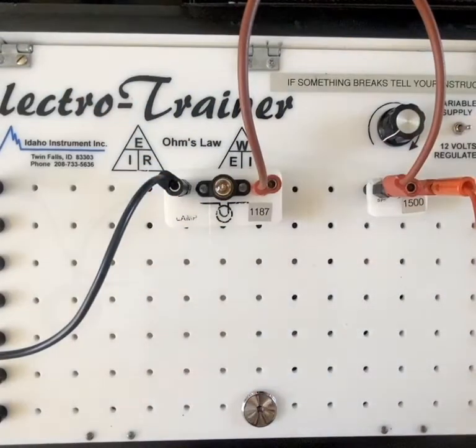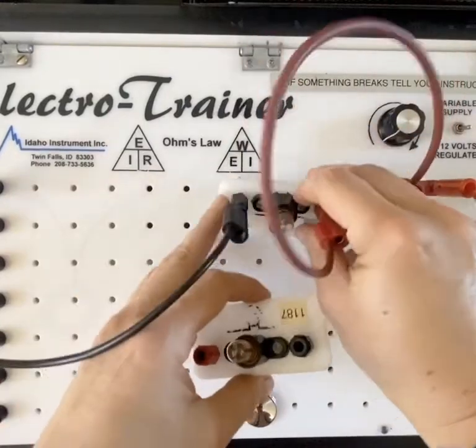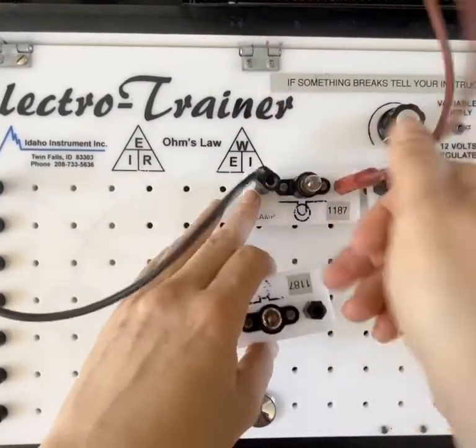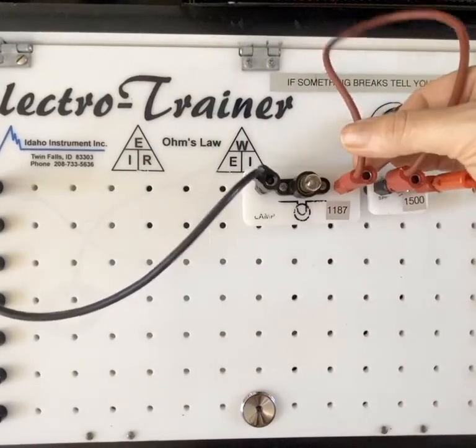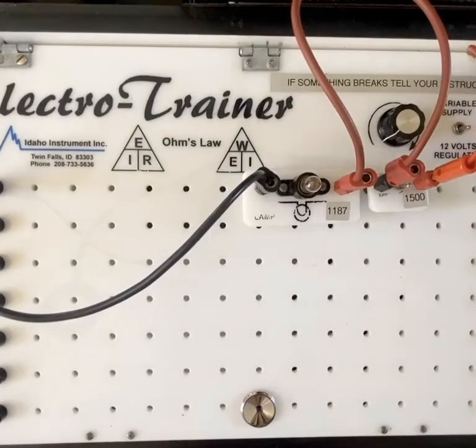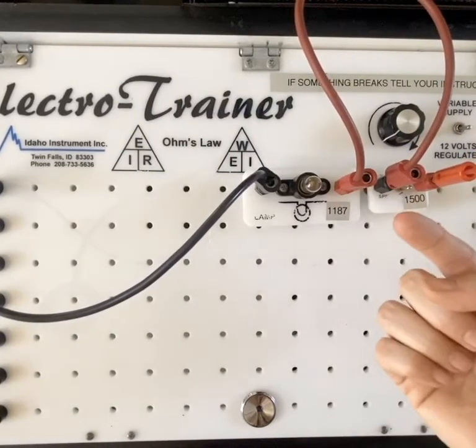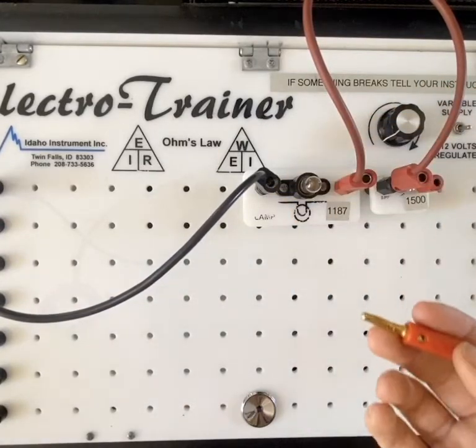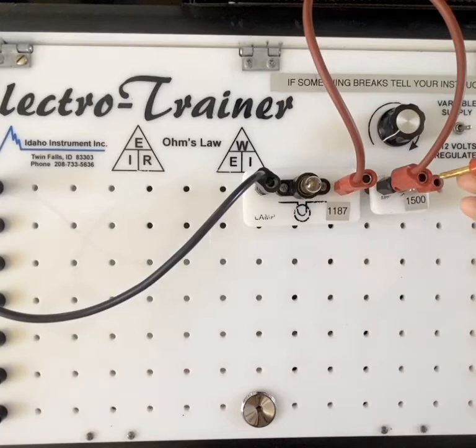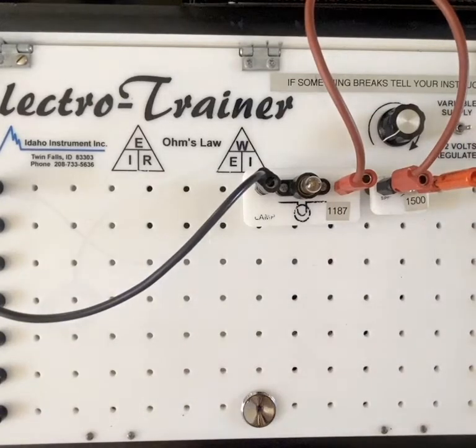So let's go ahead and turn this off here. We're going to move this one a little closer to make room. Now, I think it's really important to make note here, if you guys were building circuits in class, you would need to make sure that you are making a clear power path. It's very easy to accidentally plug wires and things where they don't belong, and we can easily create a short circuit. So anytime you're building any type of electrical circuit, even on an electro trainer, if you don't want to pop any fuses, always double check your work before you turn on the circuit. That way we don't accidentally create a small fire or pop a fuse, right?